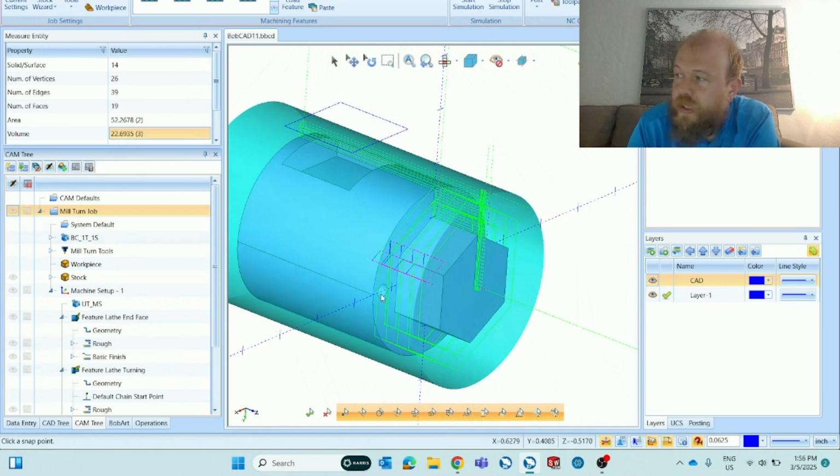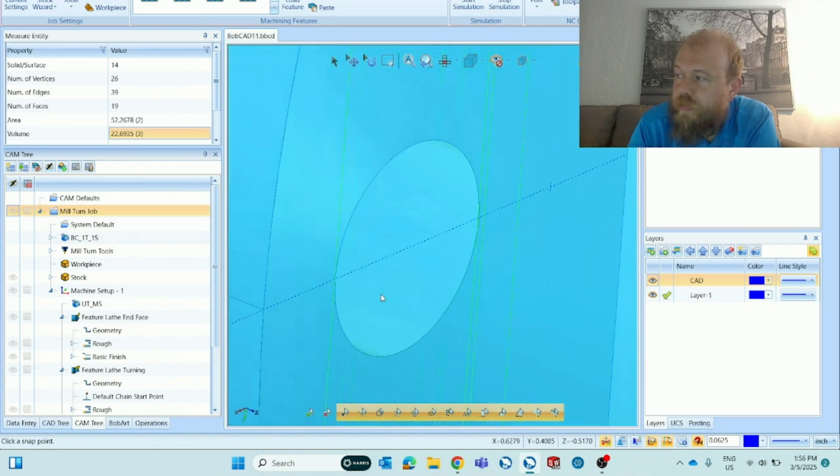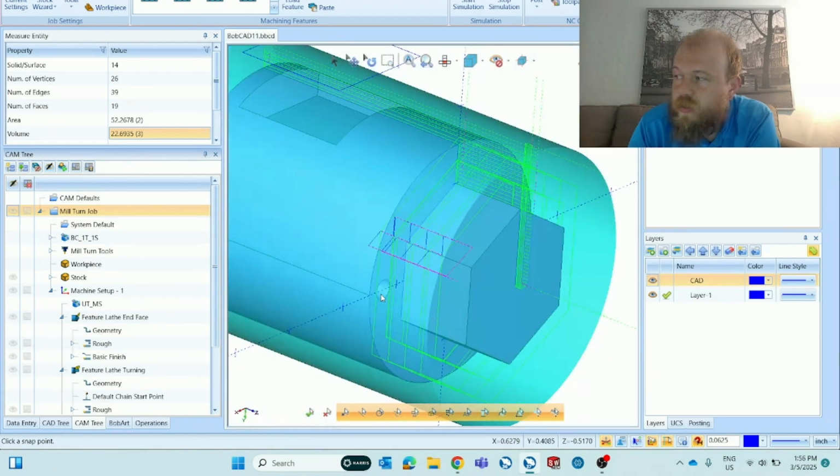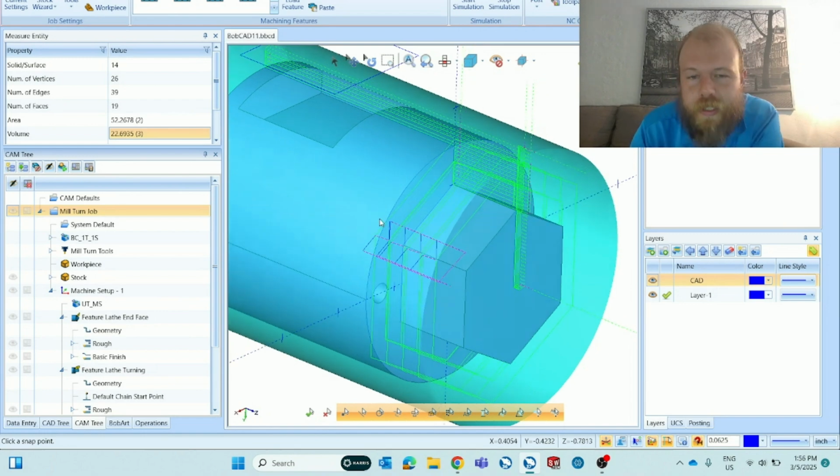Next, we'll be drilling these 2 holes from the hex into that cylindrical shape, and then we'll be indexing onto this side and pocketing this. I don't think I'll be able to do this if I don't have y-axis movement, but that's okay. We'll still program for it. We can see it in backplot. We might have to change our machine to program for that.